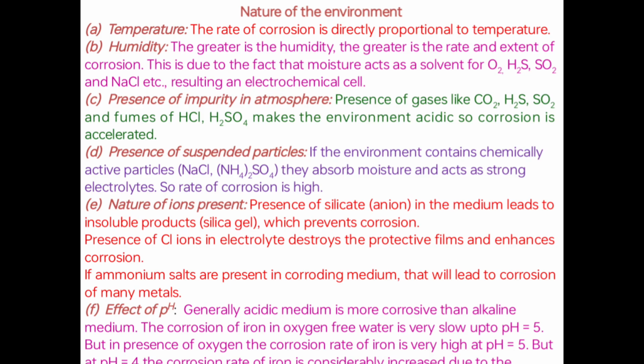Fourth one, presence of suspended particles. The environment may contain chemically active particles such as sodium chloride and ammonium sulfate. They absorb moisture and act as strong electrolytes, so the rate of corrosion is very high.